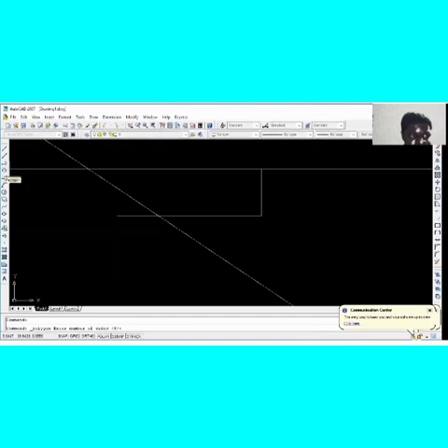Now you also have the polygon. You click on it. Looking at the command, it says enter the number of sides. Okay, let's choose 9. Press enter. You now choose the center of the polygon. You can choose any place here.